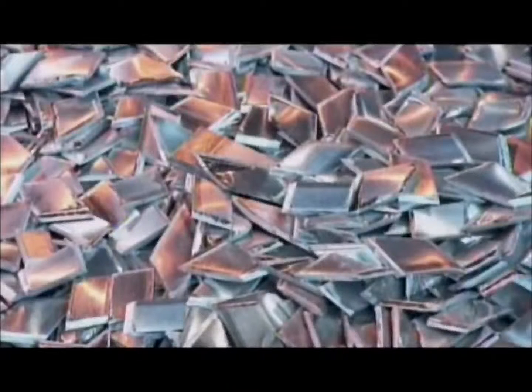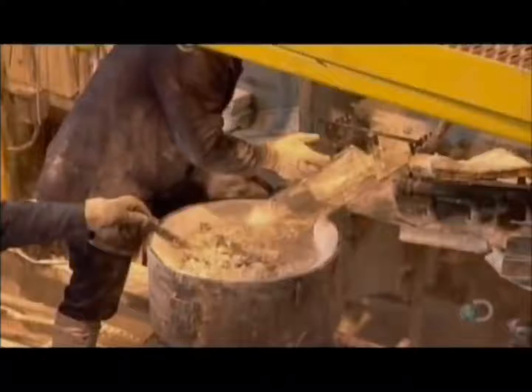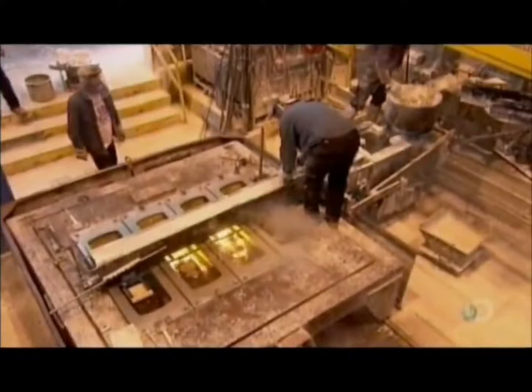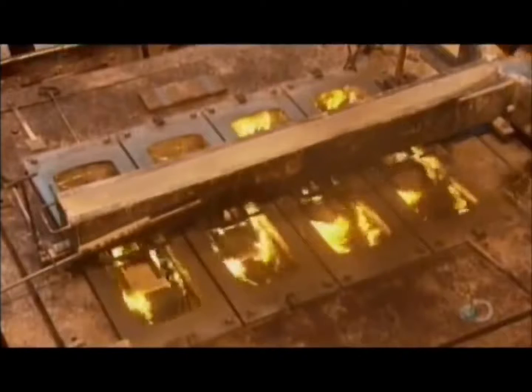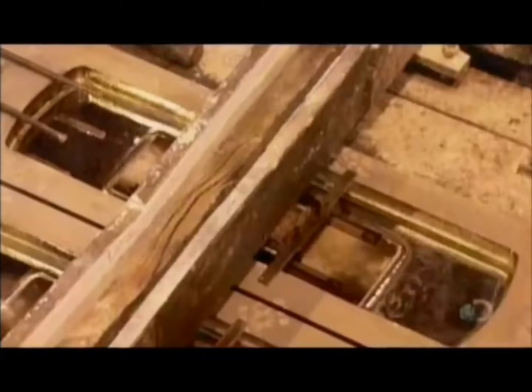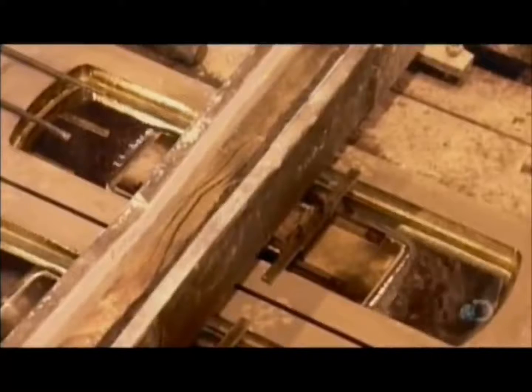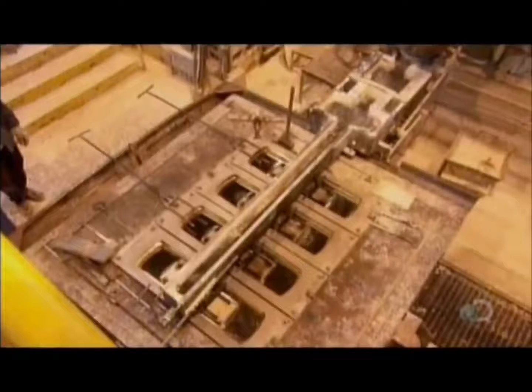We use 70% raw materials and 30% leftover from prior production, melt it into a molten metal state, and filter it to remove contaminants. Then the liquid aluminum flows into a vertical rectangular mold, and water flows around the mold so the liquid aluminum solidifies quickly. This is one of the manufacturing processes, which is casting.